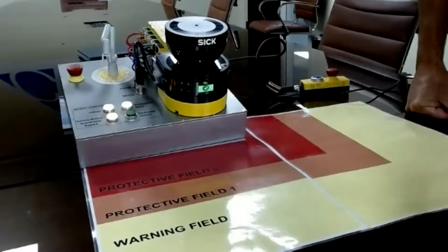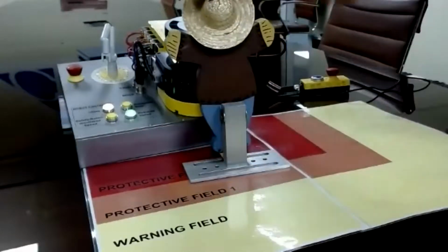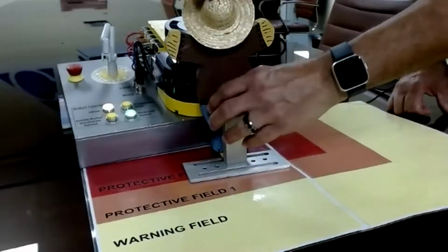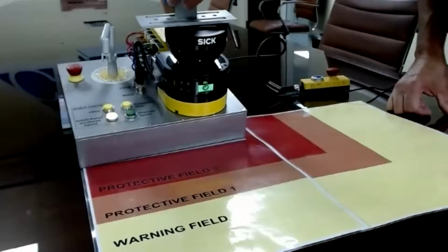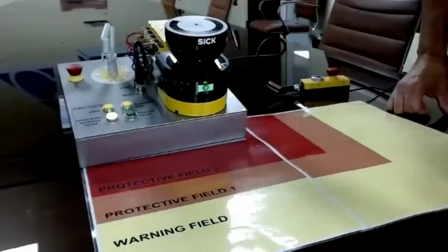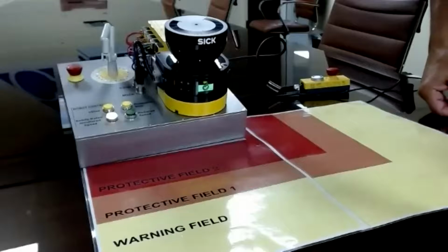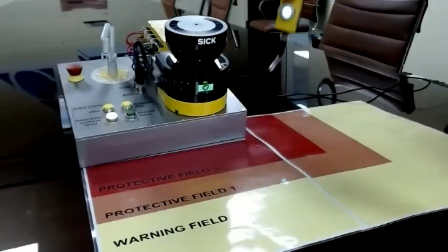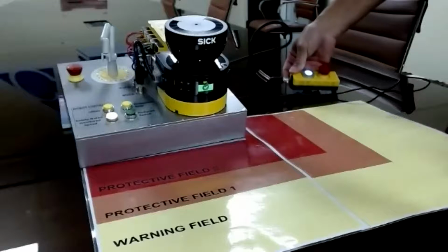So now the big question that people ask, and this is one of the things: if the person walks into the robot cell and the robot stops, and then the person decides he's going to jump up on the robot because something got jammed or whatnot, and then he gets off the robot and backs out. Well, what happens? The robot doesn't start. That's sequence monitoring. It says, hey, somebody broke the sequence. And if they break the sequence, you have to reset the robot.